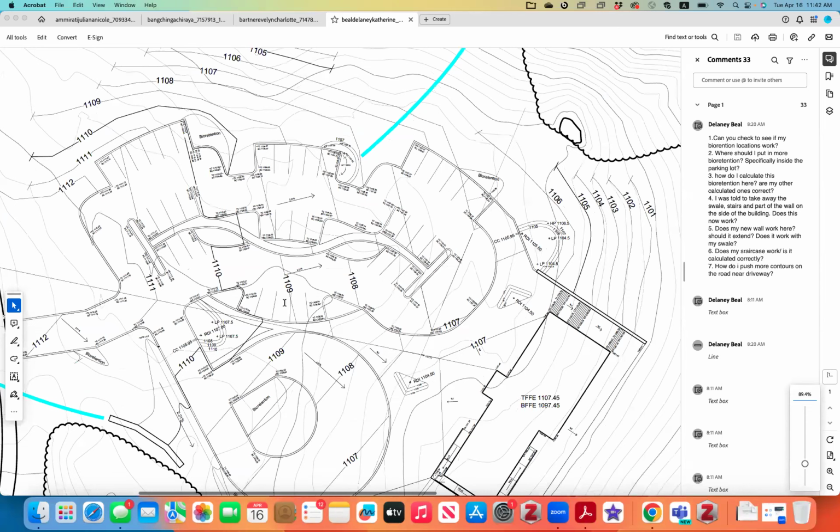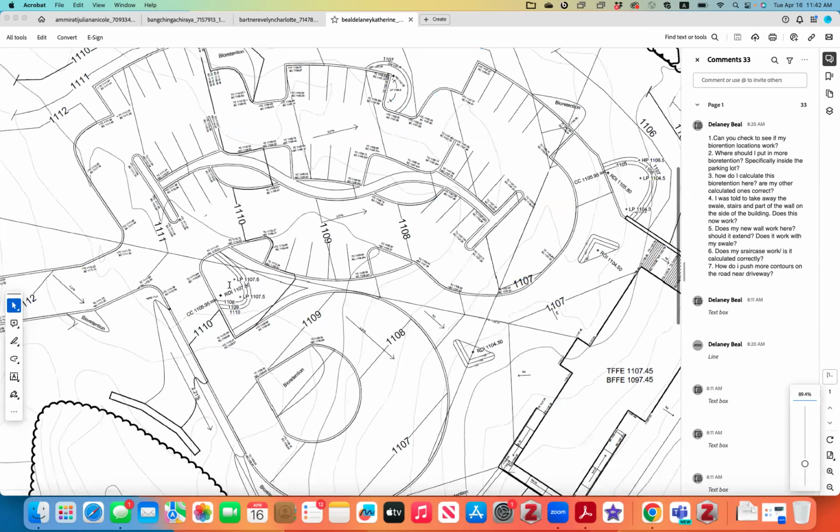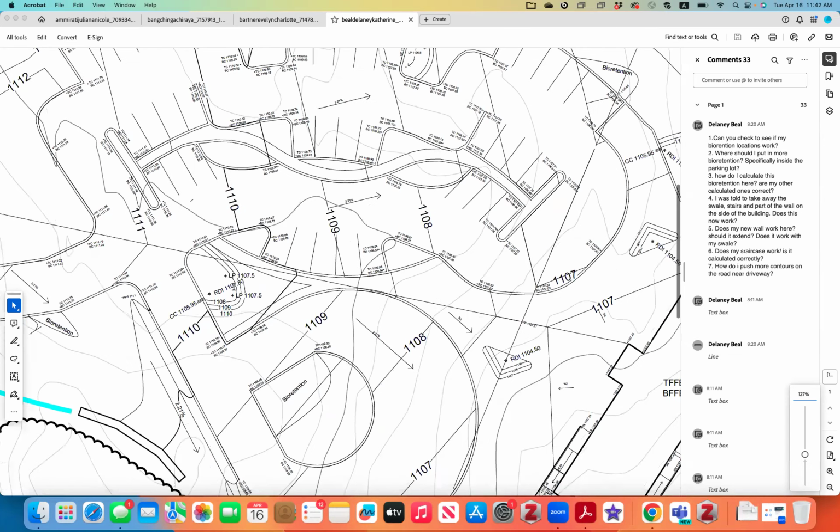On the other side, I can't tell. Okay, this one is not receiving much. Reason being, you would draw from the curb cut, right, perpendicular to a contour, and that is how much area you're receiving. That's not a lot, so I don't suggest doing that one there.